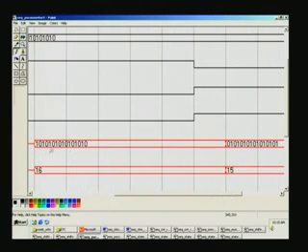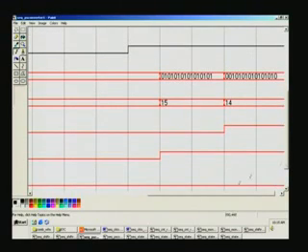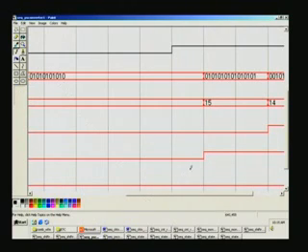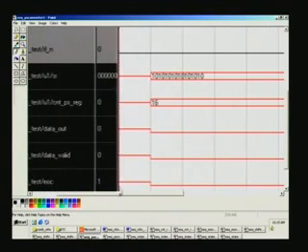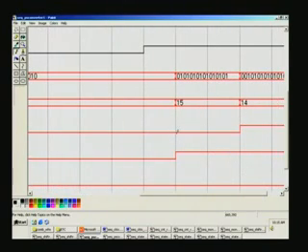So we started with 1 0 1 0. Now you can see that it is shifting 0 1 0 1 here, and also it's a right shift. Actually it was 0 here, the first bit. So what you need to get is this output. Data out is this one, immediately next. So it is 0 here, because the first bit was 0, and the second bit happens to be 1, because this is 1 here, and this is also right shifted. Like that you can see it is right shifted, as well as the last bit goes over to this.